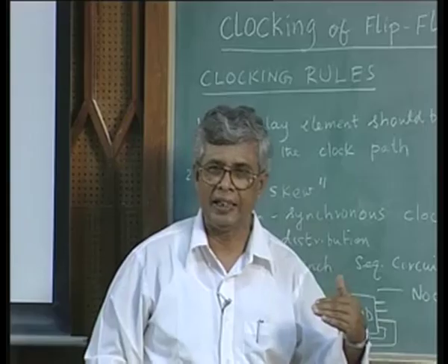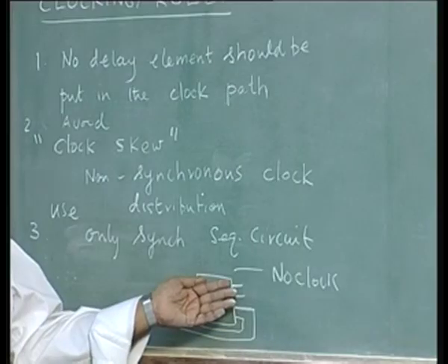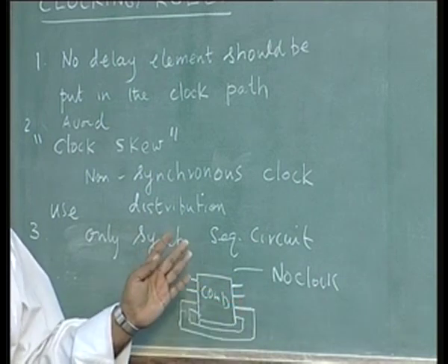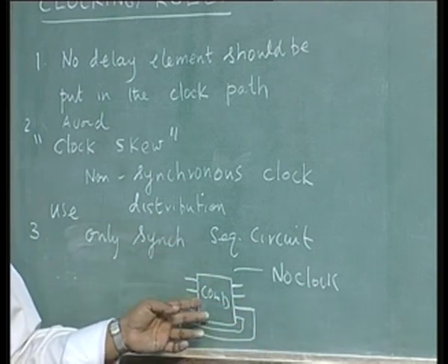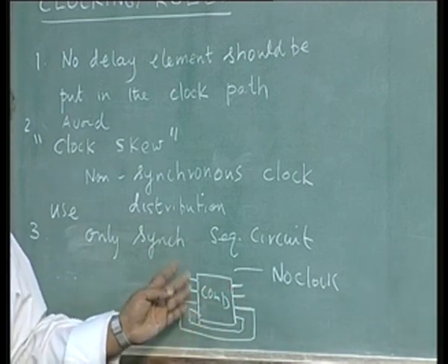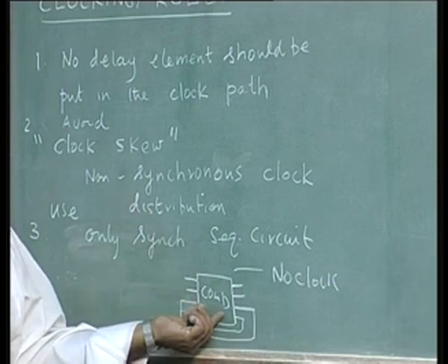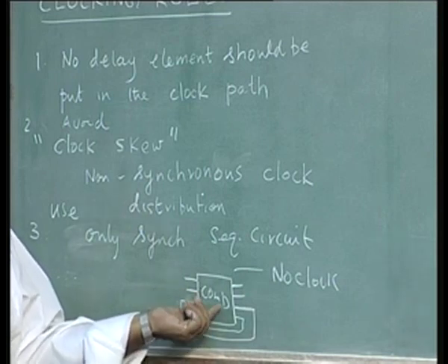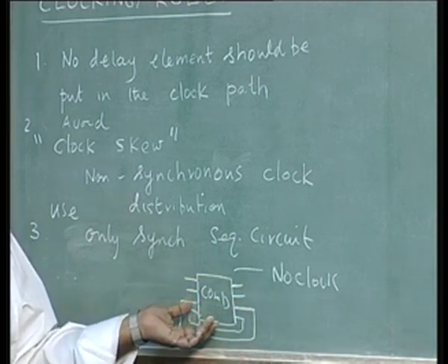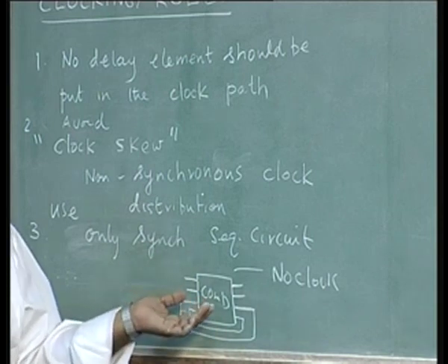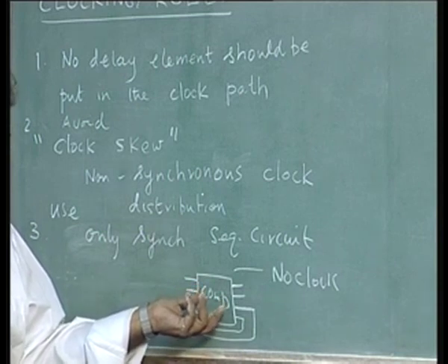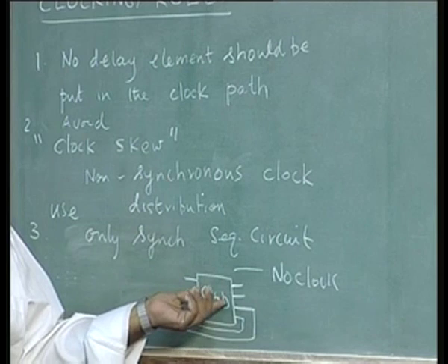A sequential circuit is a circuit in which outputs are determined by the present inputs and the previous outputs. The previous output is fed back into the gates, which will again affect the present state. So this goes on. Now there is no control when these things will happen. It all depends on the path delays of the combinational logic inside that will determine. So, there is going to be chaos inside this, especially when more than one input changes at the same time; the circuit behavior is not completely controlled by us. This is a problem.